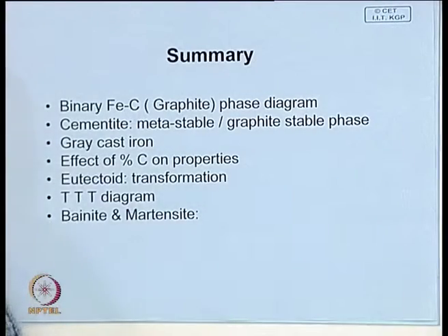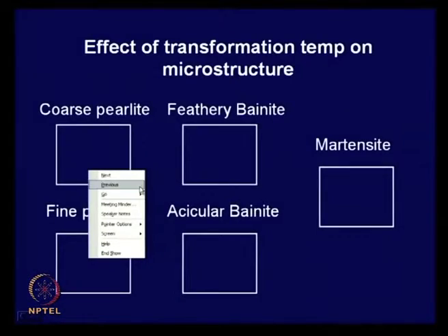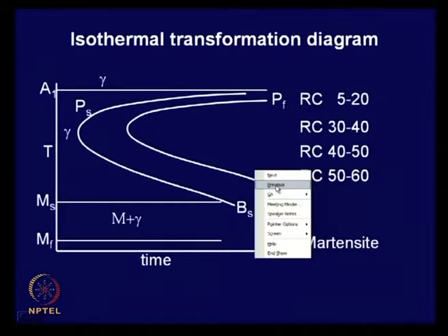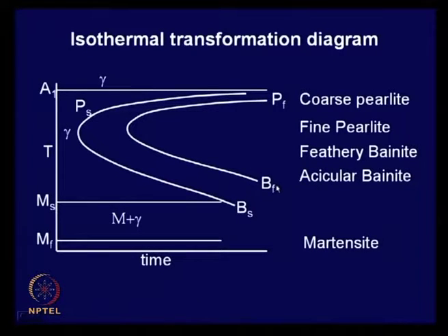And if we go back now, look at this structure. What is happening in a martensite, where you are not allowing the carbon to come out, and the structure is the fineness, and this is where it has the maximum strength, whereas the coarser structure you get in this region. So, coarser structure has lowest hardness, finest structure is the martensite.